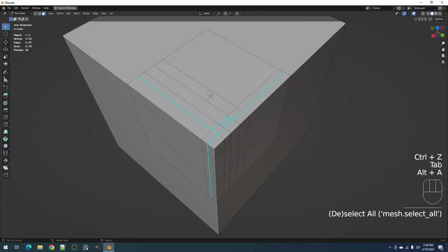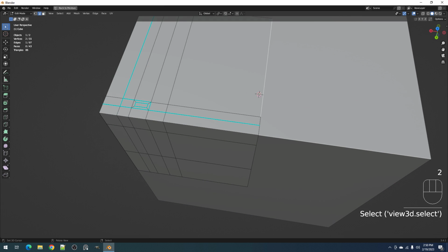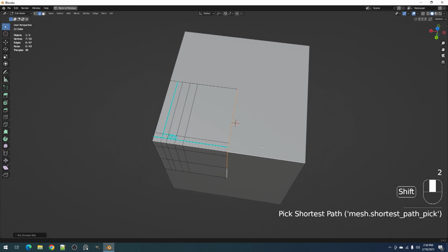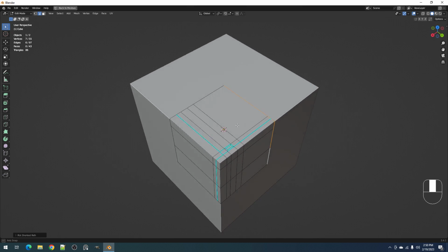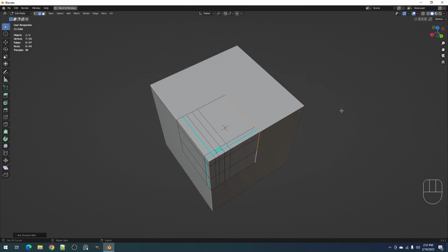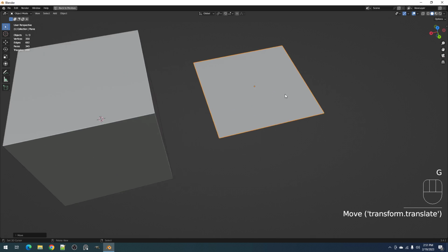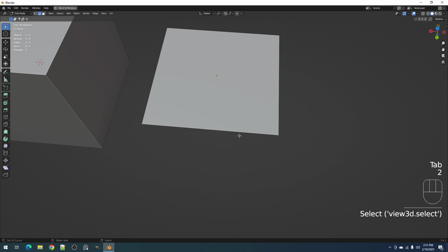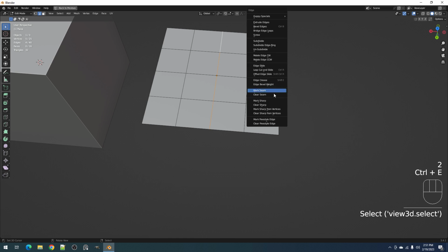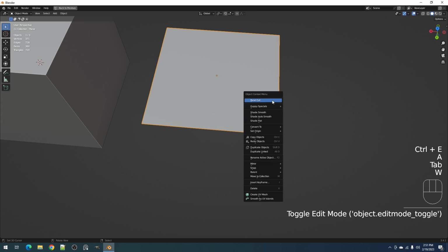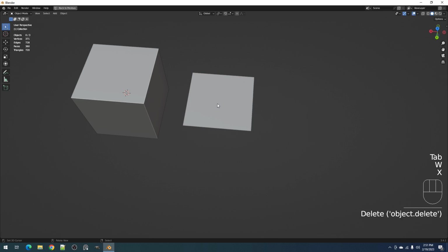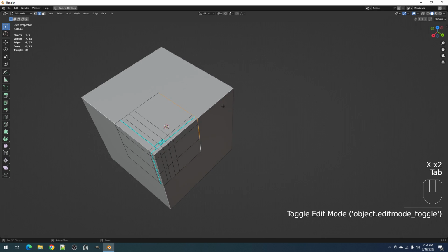Okay, so touching other mark sharp edges, or touching the symmetry line if the mesh is using a mirror modifier, or touching what we call the non-manifold edge or terminal edges. Okay, so it doesn't result in a pinch.